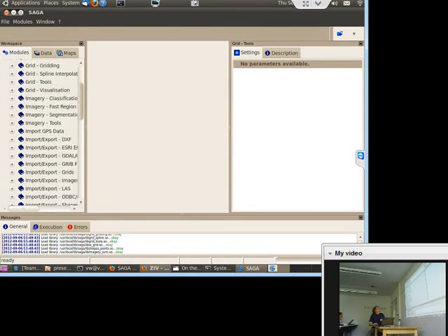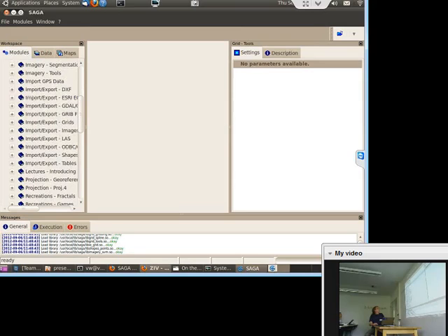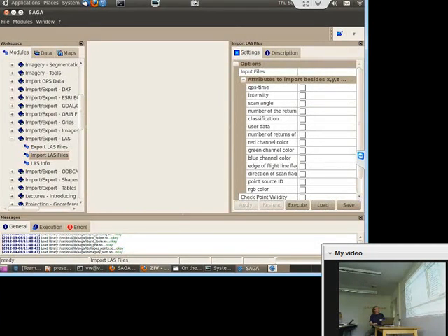In case you visualize it with a grayscale palette, the intensity really looks like a photo, more or less. This is an interesting possibility. The problem is that the intensity depends on the length of the laser beam. That is, in nadir position you have the highest intensity values, and it's getting darker once the scanner gets to the edge of the flight strip. The next step would be to overlay or merge several flight strips, and then you get inhomogeneities in the intensity values. So you would need to normalize these values before you can use them.